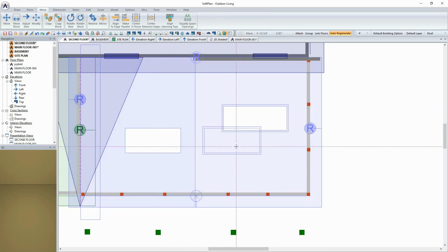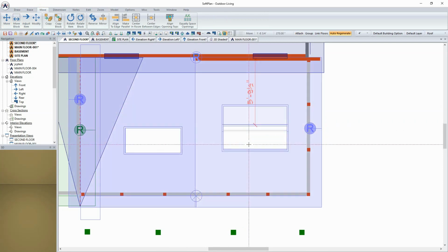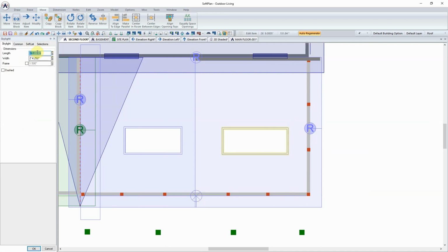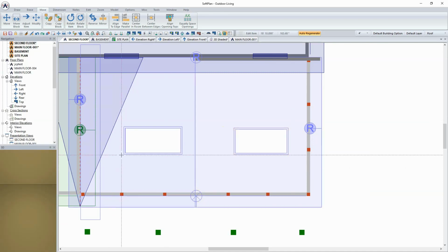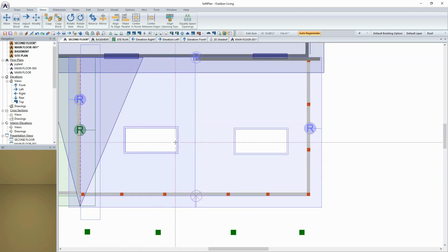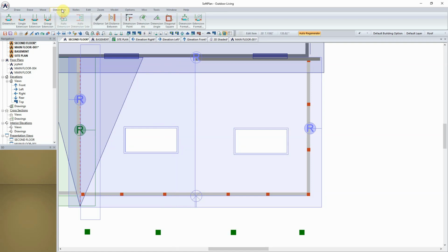If you're doing a three-dimensional model, you'll be able to view down or up and see through it. But on top of this, your bill of materials once again would be adjusted. These skylights can be moved about on the plan and can be edited once they have been placed, so that items such as length and width could also be modified on the actual drawing. This allows you to go in and accurately set up the size of what this is going to be, and then through the edit and repeat edit you can of course apply the exact same change.